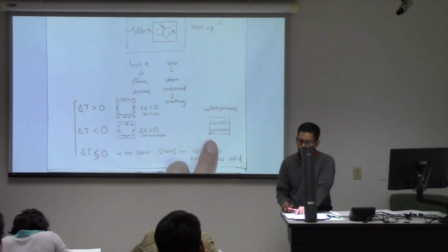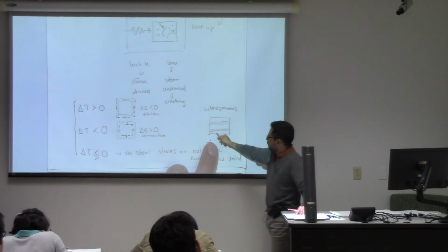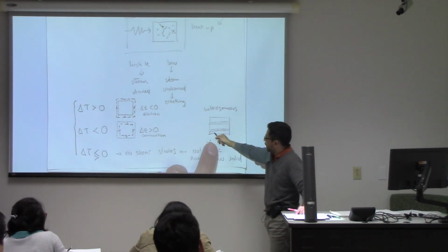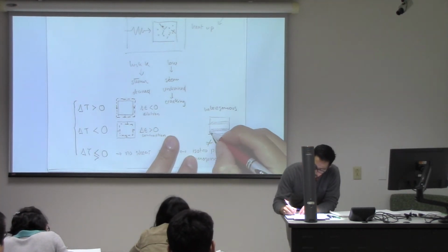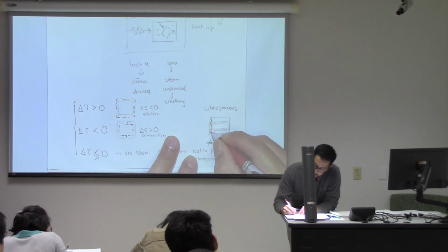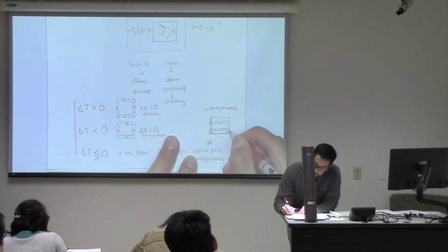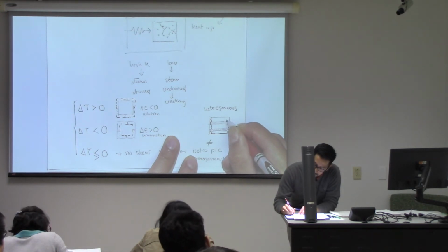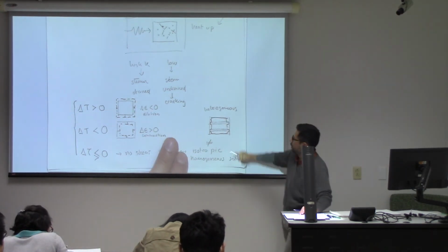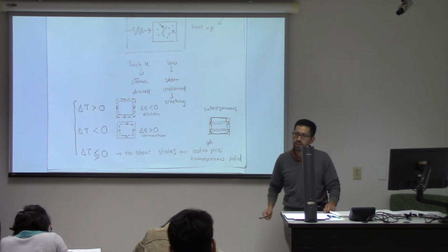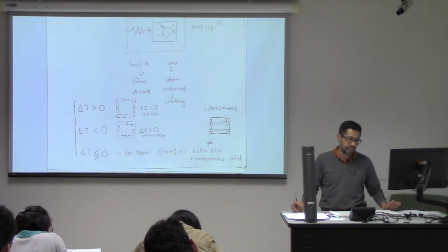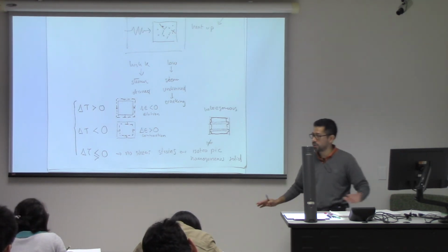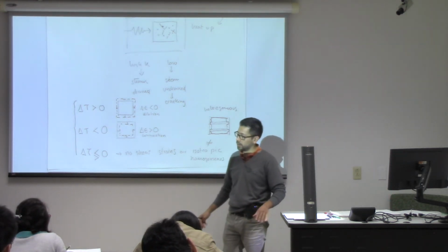If you were to say this one shrinks more than this one, if you were to deform this under no constraints, it will shrink like that, right? And very likely you will have a lot of shear strain in the interfaces. So for an isotropic solid, we can assume that. But if you have an anisotropic heterogeneous solid, it gets a little bit more complicated.